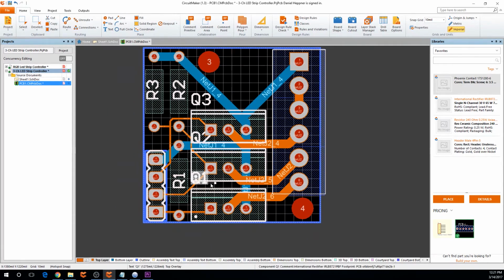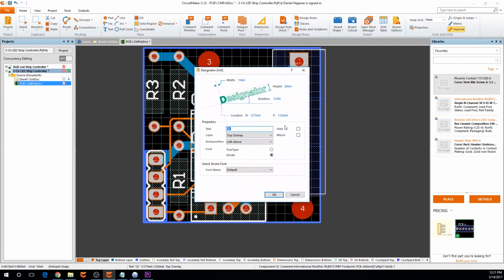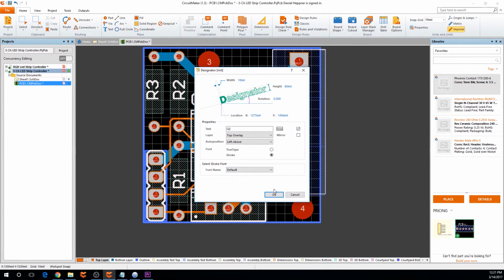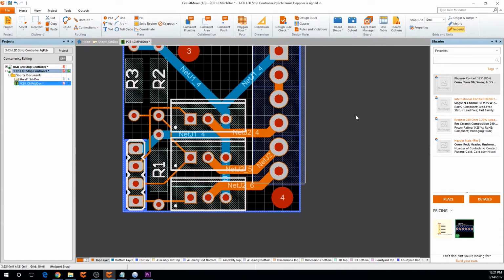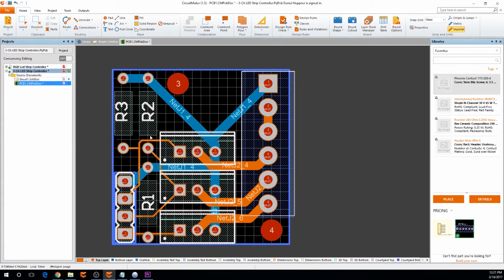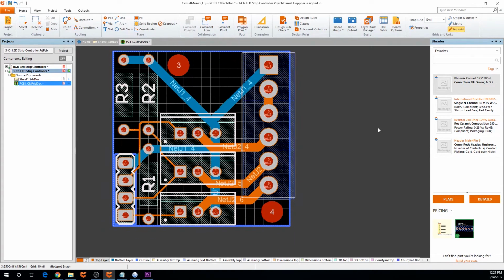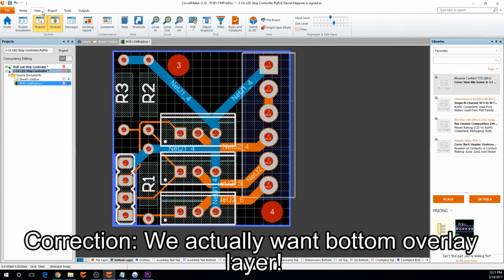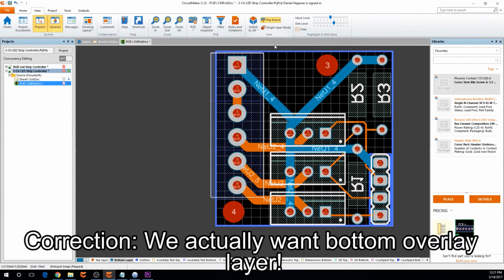Okay, good. Last but not least, let's get rid of these. Looks like they are locked as well, so we can just hide them. Good. Alright, so that's all the text gotten rid of, besides the resistors. Those are fine. Now, I'm going to want to go on the other side of the board. So to do that, we're going to switch to the bottom layer. We're going to go up to View and then Flip Board.